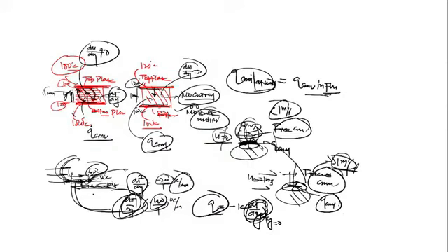Clear? So a higher velocity gradient is responsible for a higher temperature gradient, and that is why there is a higher rate of heat transfer by conduction at the wall, and that high rate of conduction at the wall is transferred into the rest of the fluid by convection. Yes or no? Any other doubt?